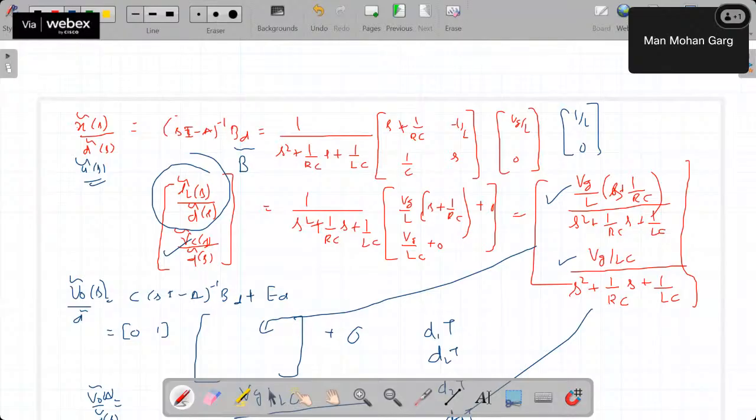So now T1, T2, T3, T4, these 4 times of 4 different modes, must be a function of some duty cycle. Definitely, if there are 2 switches, 2 duty cycles will be there, 3 switches, 3 duty cycles will be there, right? Now, once you have this, you multiply each mode's equations with these time intervals, then divide by T. So capital T will cancel out. Only the state variables, system parameters or these duty cycles remain, right? And the same approach we follow.